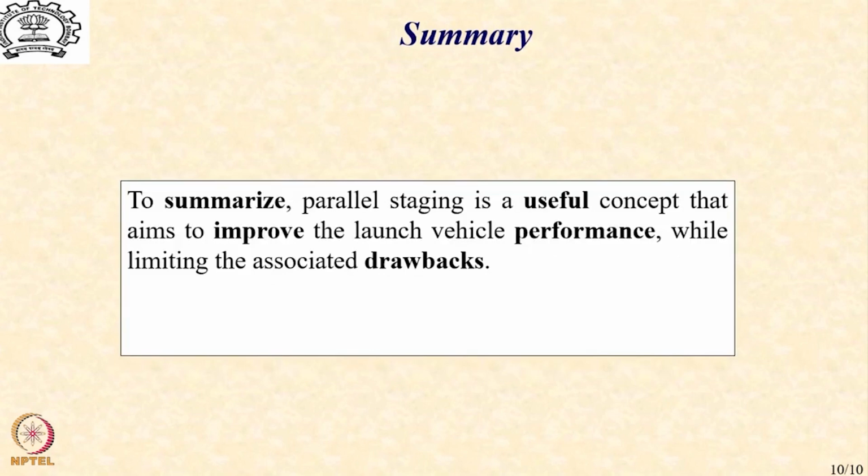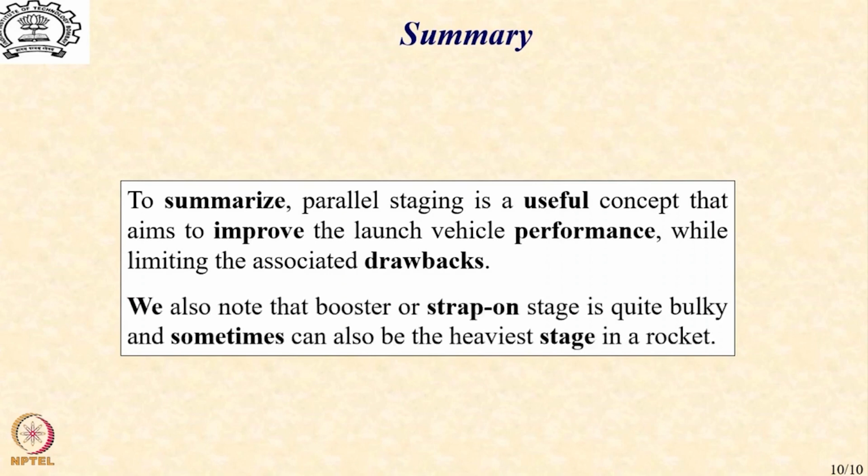So, to summarize, parallel staging is a useful concept that aims to improve the launch vehicle performance while limiting the associated drawbacks. We also note that booster or strap-on stage is quite bulky and sometimes can also be the heaviest stage in a rocket.